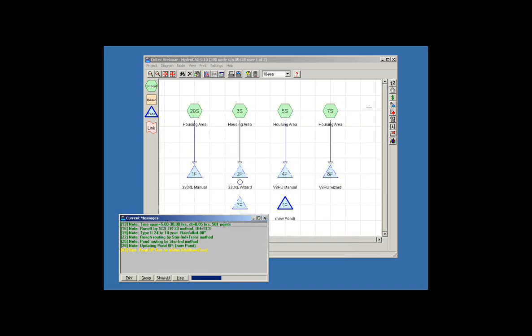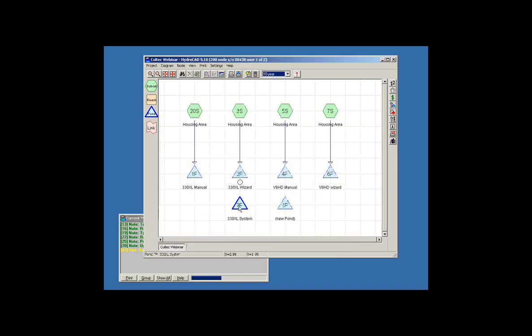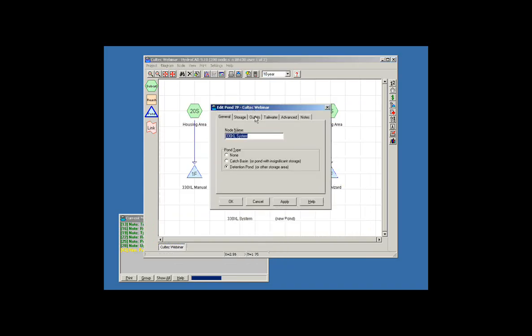So that's the basic process that you can use for setting up any of these systems. And the HydroCAD chamber library lets you pick any of those CULTEC chambers or other products, even pipe storage, which is handy for doing a comparison. As Gina has pointed out, or Fred has pointed out, it takes a lot more height to put in a pipe system. So you could rough in a pipe system of comparable storage, and this would tell you how it would compare with a CULTEC scenario.